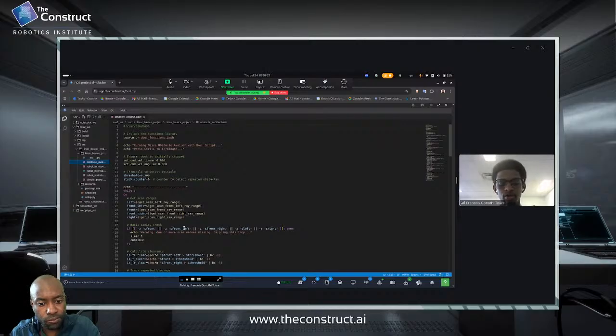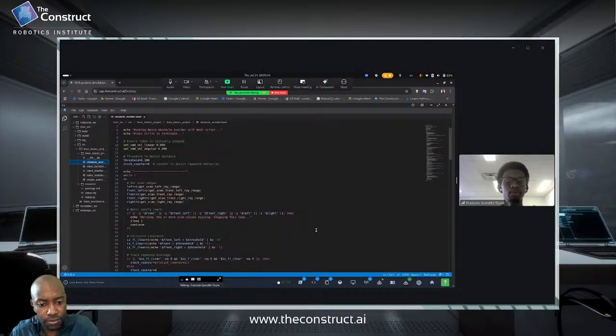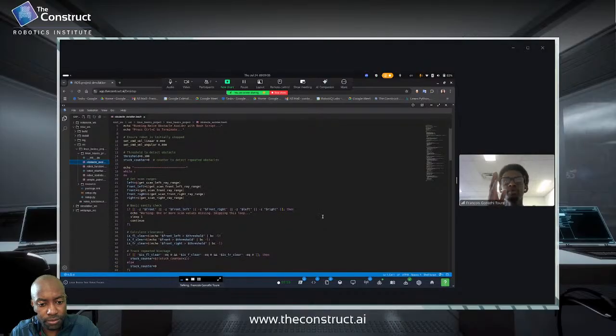It also implements an 8-case decision tree for the robot movement, because it shouldn't just detect the obstacle and stand there. It has to move, and it avoids collisions by checking a proximity threshold, which is the question you were asking before. Yes, it's 0.3 meters. On top of that, the angular velocity changes when obstacles are near. That's what we were saying in the simulation.